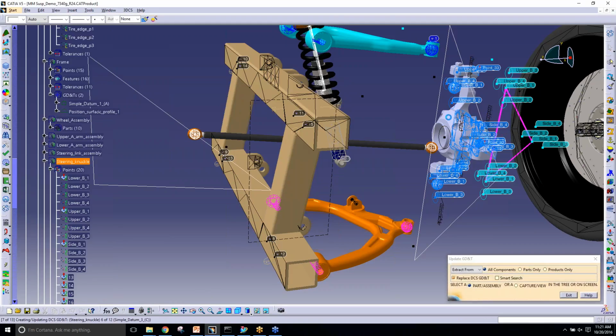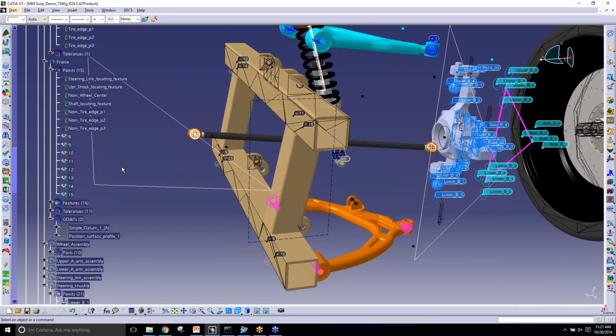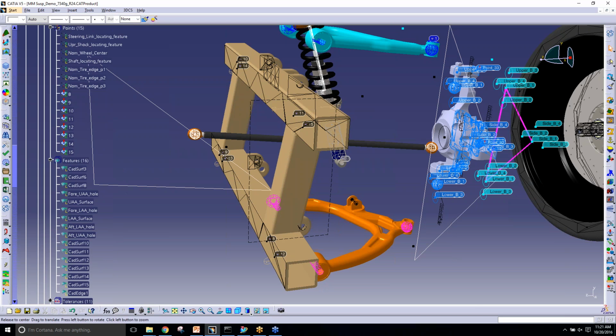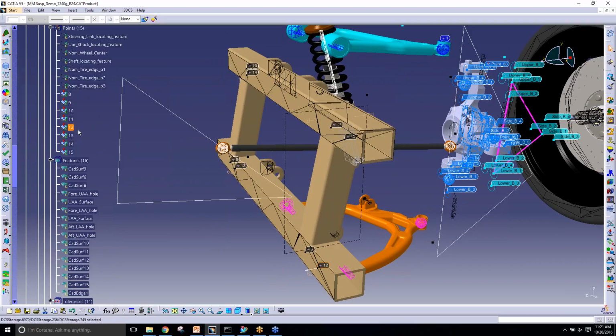So this is pulling over, you said, if there are datum features, it's pulling that. It's got the tolerances. It's got the CAD points, all being drawn in straight from the CATIA and automatically being applied to your model. Right. So if your model's already been toleranced and had GD&T added to it, there's no need to add 3DCS tolerances unless you've got additional tolerances you want to add onto it, or if you're doing something like the fixtures or additional process.